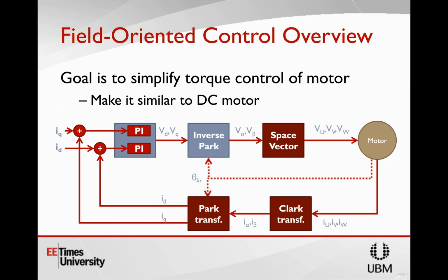And so these represent actual real values in our motor. The direct axis, or the direct vector, is also called the flux vector. So it represents the amount of current that's either helping or detracting from the magnetics in the motor. And since our permanent magnet motor has all the magnetics it would need, we don't really need to do any additional current there. So for most applications, this ID value, the desired value, is always set to 0.